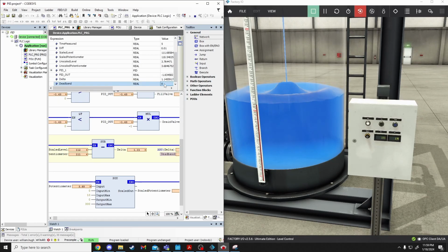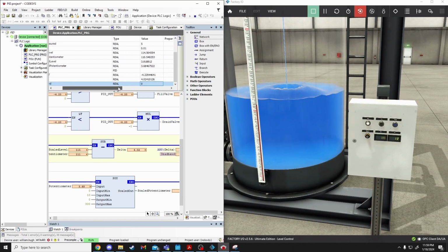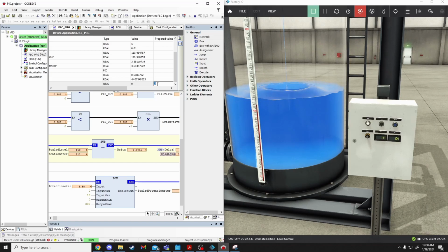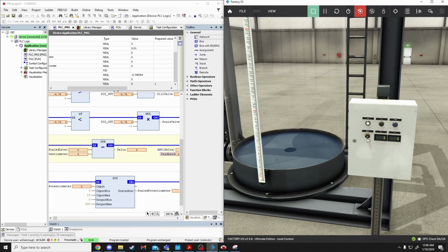So let's set our deadband. Let's set a value of 1. Let's try that. That'd be twice as tight of a tolerance as the 2 was. So let's try and pull it out of this oscillation. Ooh, it's going. This would be a good time to have a stop or a reset plugged in, and you can just bypass the PID and stop this from happening. But we are just trying to control the PID today. Okay. Broke it.